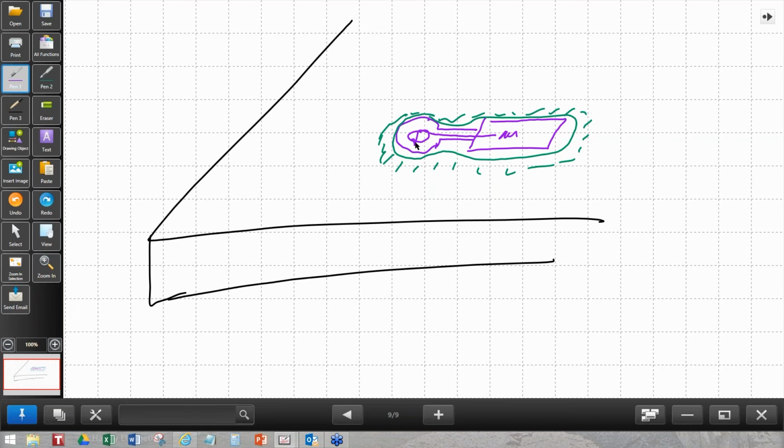What can you do? Well, after the fact, number one, it's best to make sure that the distance between those two is sufficient that you can run the solder mask between them. That's number one, but that's after the fact. The horse is out of the barn. So what can you do here?